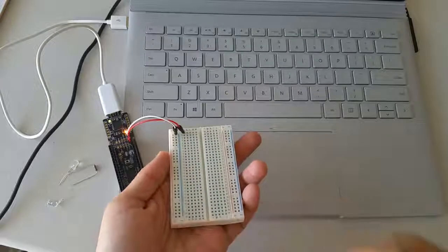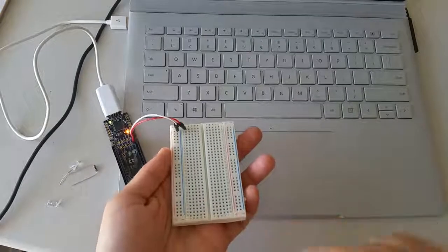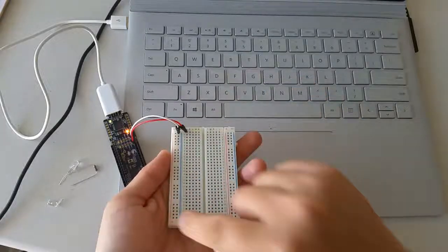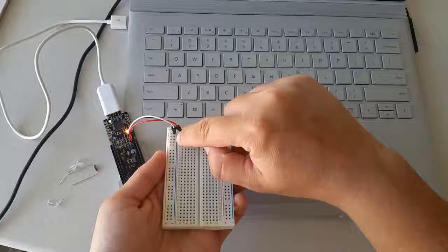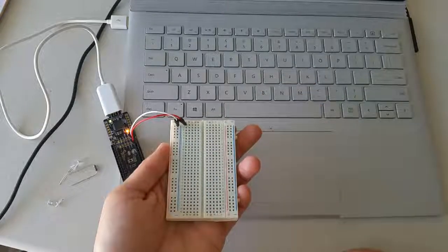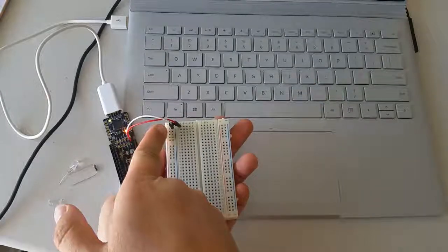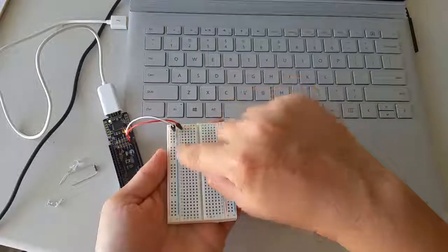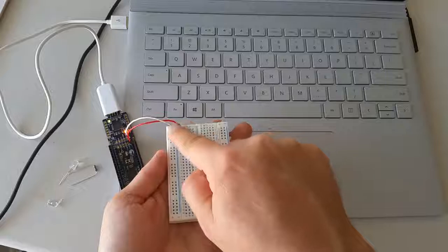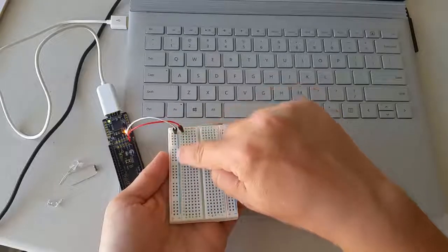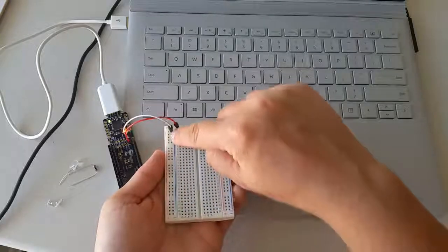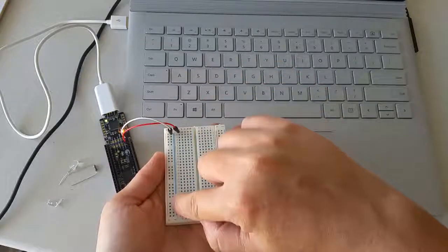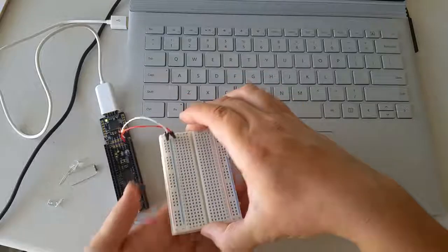On the left-hand side and the right-hand side of this solderless breadboard, one of the columns has a red stripe next to it, and one of the columns has a blue stripe next to it. Oftentimes, we will use the red stripe to be power and the blue stripe to be ground. So by using a jumper wire to connect one of the pins in the blue stripe column to ground, we will make all of the pins in this whole column all connected to ground.